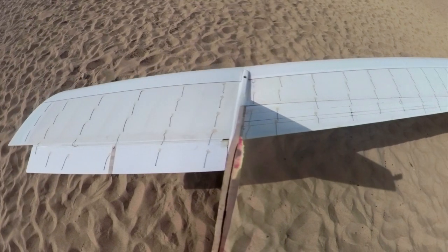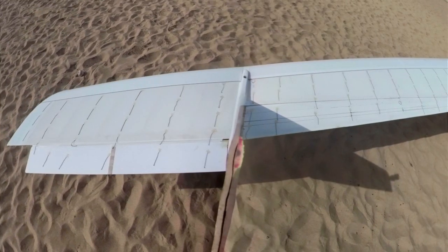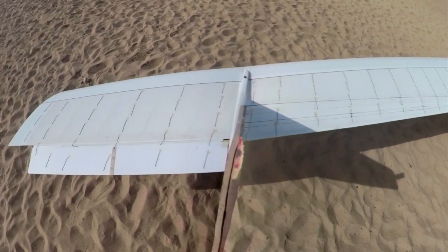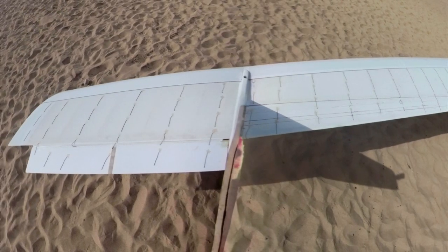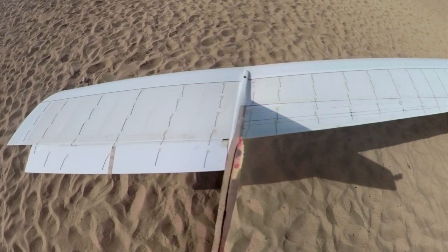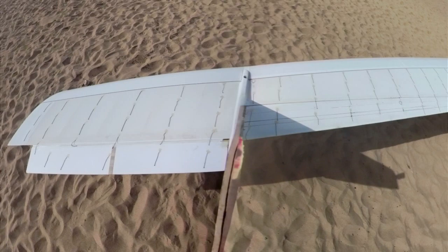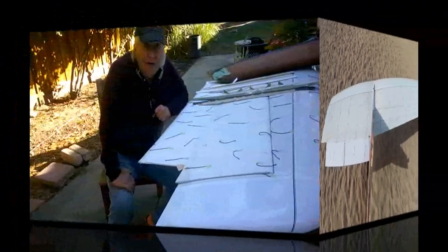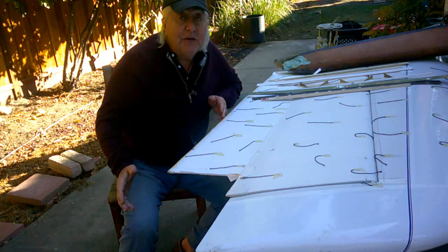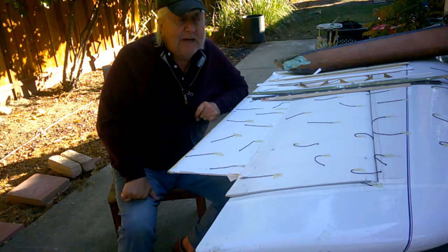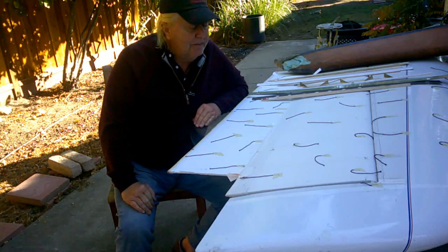And I did a series of little taxi test ground runs here where I'm pitching the aircraft up and down, taking it up to stall and back down again. I had very precise pitch control over it. Never had any sense of losing control. I didn't do any roll reversals, but if there was separated flow and oddball drag, I would have noticed it here. It's very clear that with the Elevons being larger, I had much more roll authority. In fact, I doubled the roll rate of the aircraft with those extended Elevons.